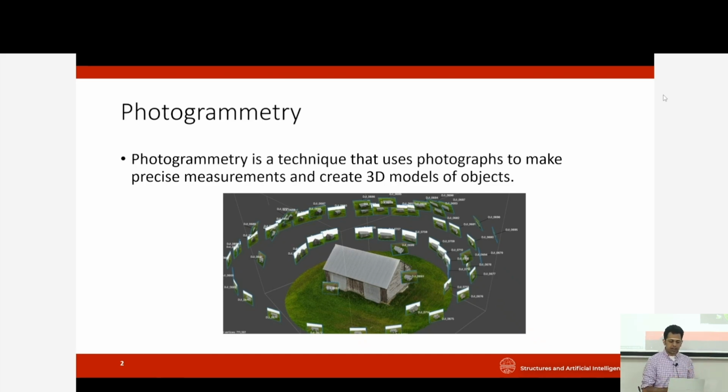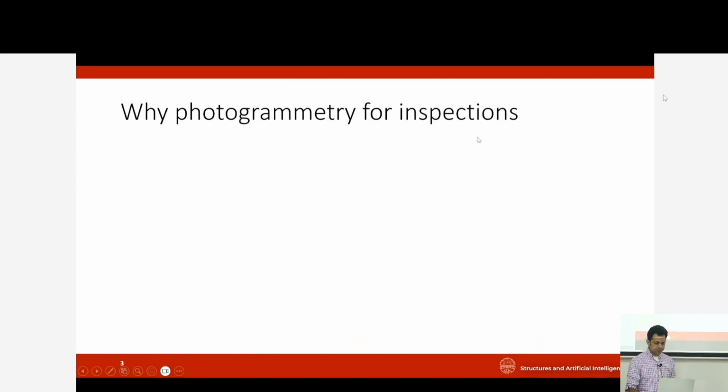which is often the case when you're doing inspections, you want to get an overall view of the asset. For example, if you have a picture of just a zoomed in part of a structure which is not damaged, that is not sufficient to make an assessment about the whole structure. So that's why being able to put each of these images in context is a very valuable tool when we're trying to use the data that we've collected to make decisions about the integrity or health of an asset. So that's why it's important, and that's why we're going to look at different aspects of this.